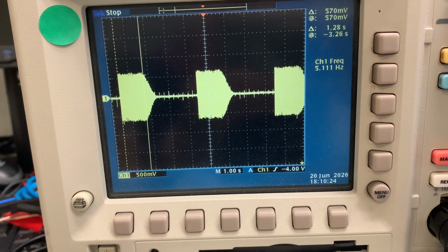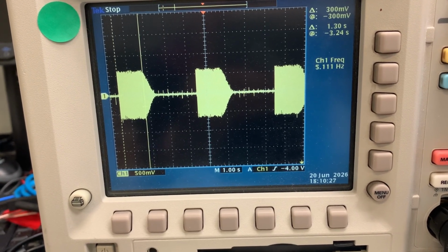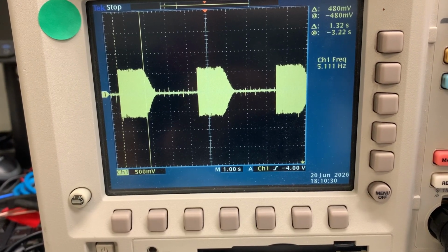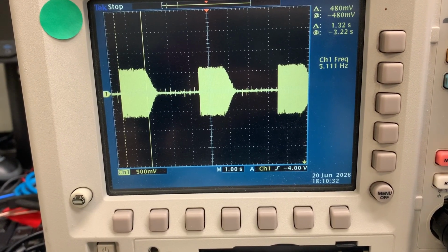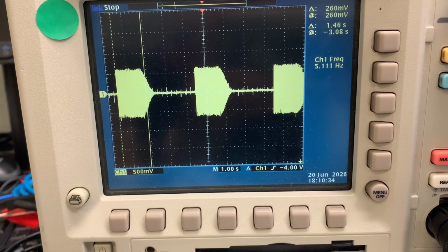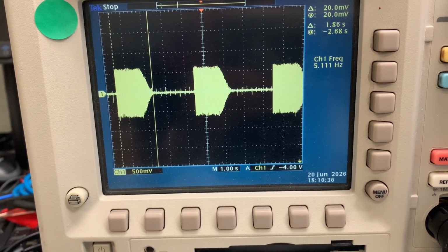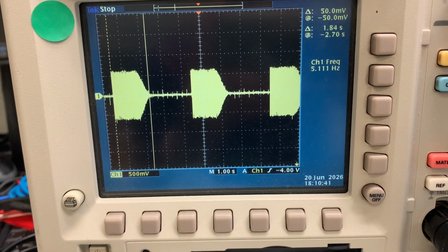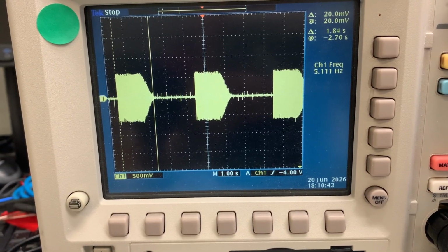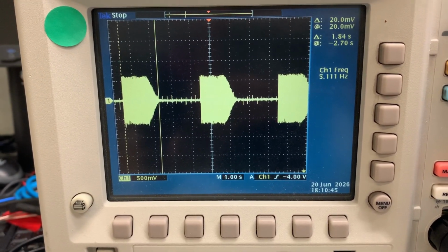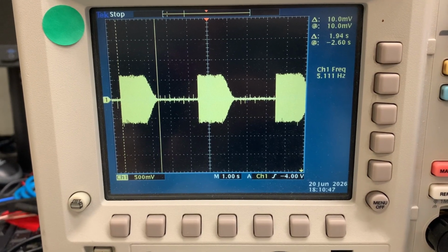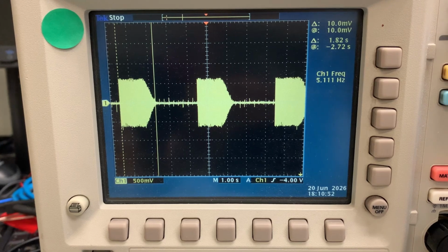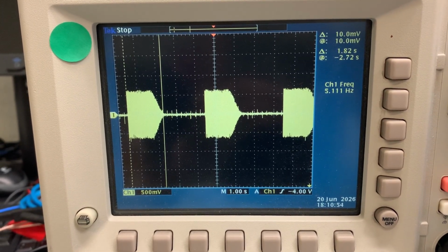The interesting thing to notice here is that at some point during the sweep the frequencies start to roll down. Right here, after about 1.3 seconds the frequency starts to lose its power strength and gets attenuated more and more till you see nothing. So after, let's say half the time, after 2 seconds, roughly around 20 kHz, basically you see nothing. From 20 kHz all the way to 40 kHz, all the signals are completely suppressed, completely attenuated.